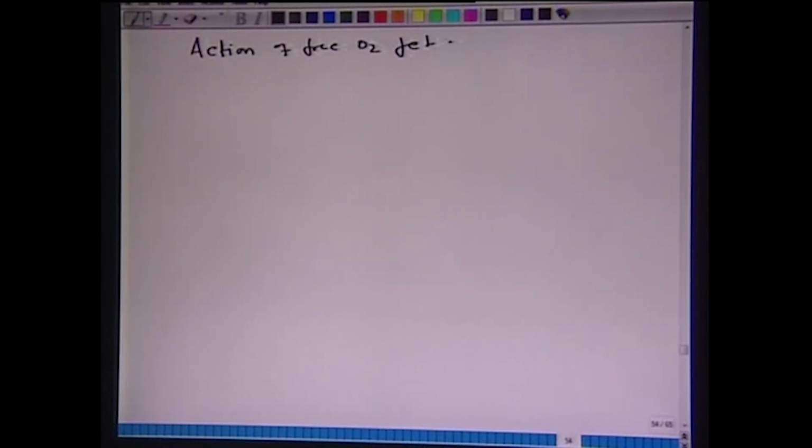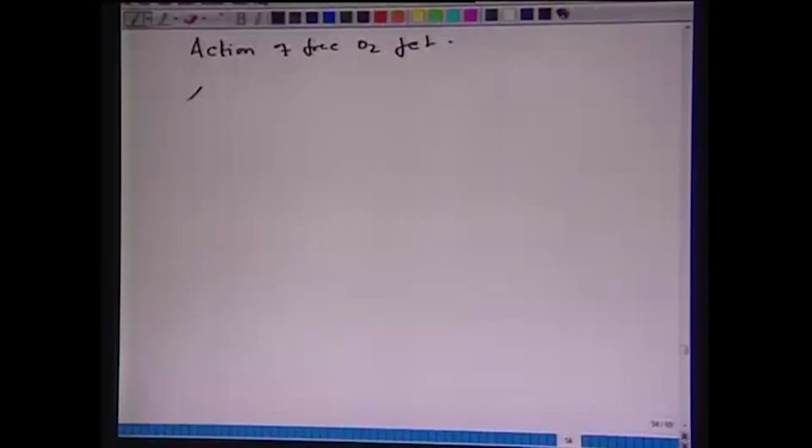Now, as I said, it is difficult to find out the velocity, but you know that the mass of the jet increases downstream with distance, and the velocity of the jet decreases. So, the momentum of the jet, that is m into v, is conserved downstream of the nozzle. That means the momentum flow rate within the jet is constant, and that is a very important property. Now, we define a term which is called dimensionless momentum flow rate.